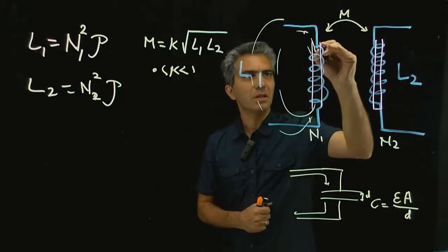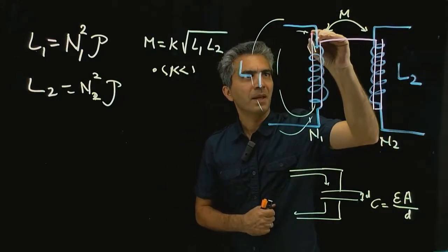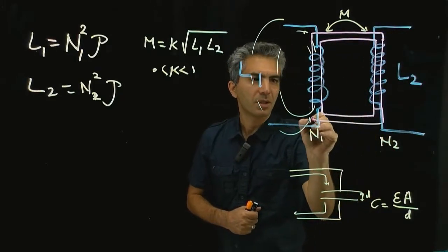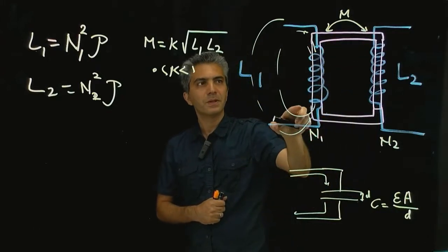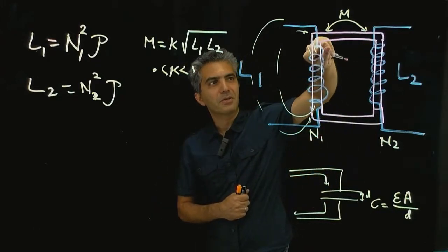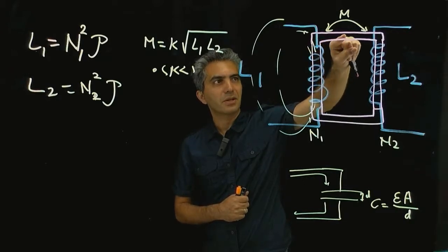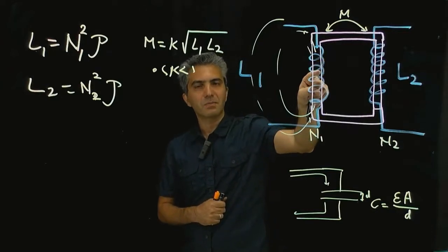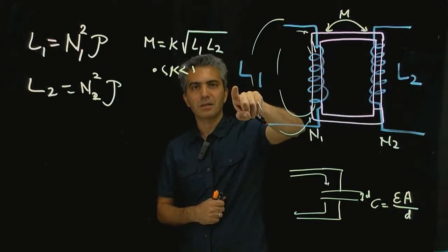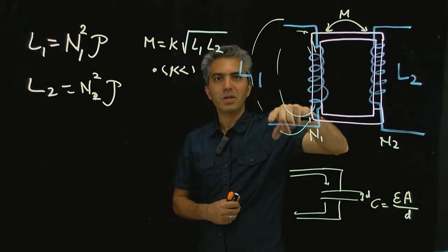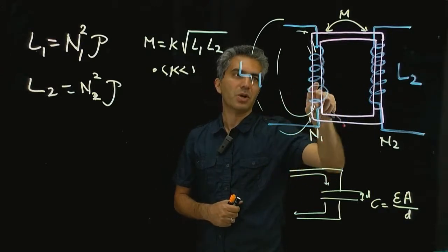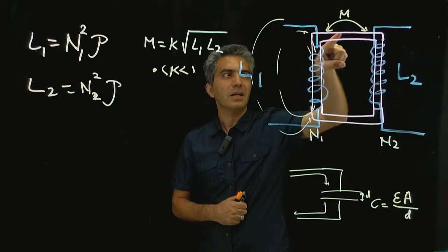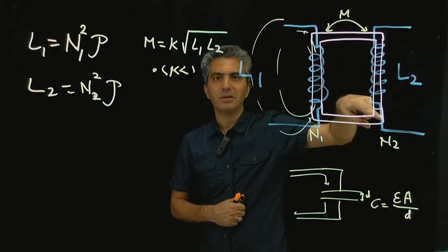Now, what you can do is take this idea and make a loop. In other words, take this material and turn it into a loop. Now the magnetic field that is created in one is going to continue and go through the other one. Since we already said that if this permeability is large, I can ignore anything else outside, we reach a limit at which I can say that all the magnetic flux density that I have here is going to pass through the other inductor.